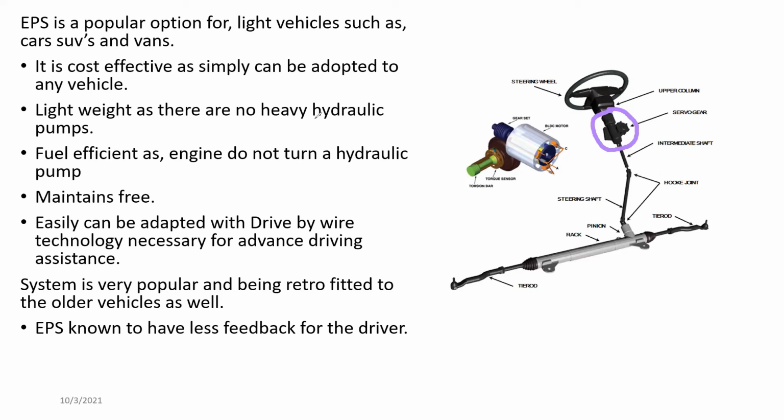And fuel efficient. This is very fuel efficient, because there's no pump driven by the engine, so there's nothing to rob some of the engine power. And maintenance free. No hydraulic fluids or anything needed here, right? And it can easily be adapted with the drive-by-wire technology necessary for advanced driving assistance. Now, this is an important part.